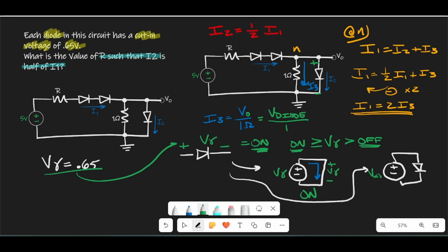When a diode is off, it doesn't allow any current to pass. It acts like an open circuit, and you'll have to calculate the voltage that it stores with some more circuit analysis. All you know is that the voltage will be less than the turn-on voltage. And just like that, bam, you are now equipped to deal with about 80% of diode problems. Congratulations on leveling up to an electronics guru.